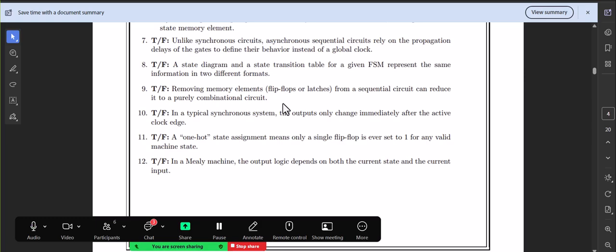So your states would be 00001, 00010, 00100, and so forth. So the anode display is one hot. It's active low, but it's the same thing.